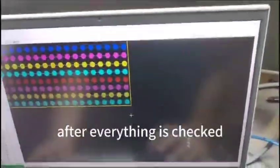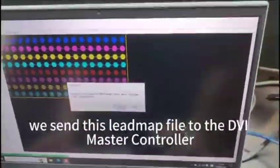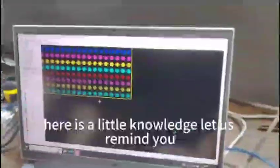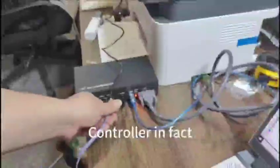After everything is checked, we send this LED map file to the DVI master controller. The other options are all in the default values. Click OK and the sending is successful. Here is a little knowledge. Let us remind you, now the LED map file has been sent to the DVI master controller.